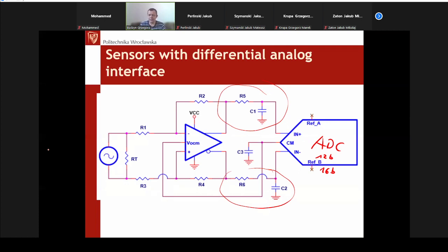So it's not that you can connect a sensor directly to a microcontroller and utilize 1/10 or 1/100 of the ADC resolution, and then everything else do by signal processing. It's not true. So don't believe it if anybody says so, or wants to convince you to this view.